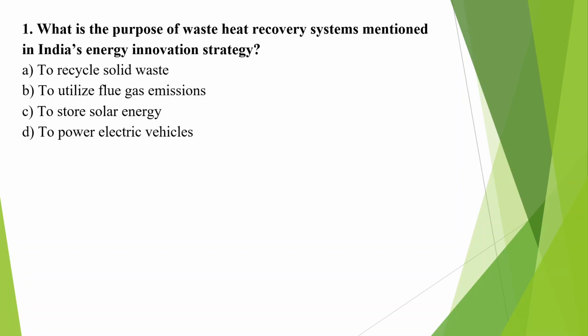So instead of heating our fluid or water from the base temperature to the required temperature, we utilize the flue gas emissions temperature to recover or extract some of the heat, and to give some initial heat to our actual primary fluid. That's why we call it waste heat recovery.